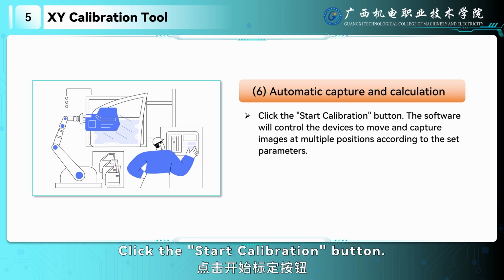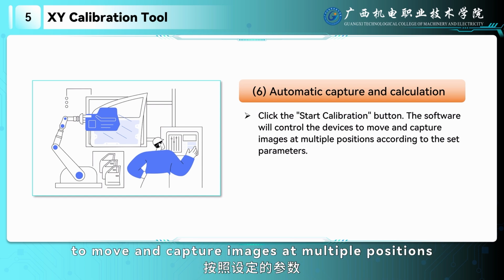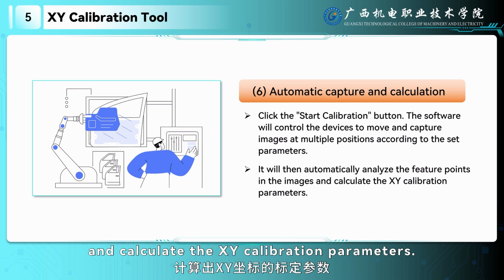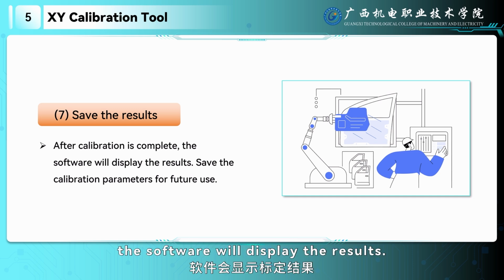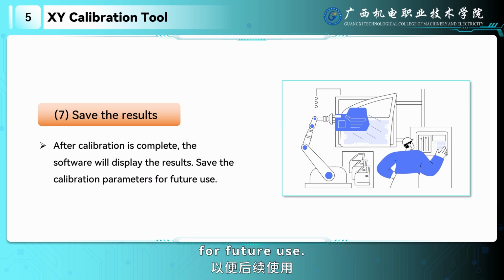Click the Start Calibration button. The software will control the devices to move and capture images at multiple positions according to the set parameters. It will then automatically analyze the feature points in the images and calculate the XY calibration parameters. 7. Save the results. After calibration is complete, the software will display the results. Save the calibration parameters for future use.